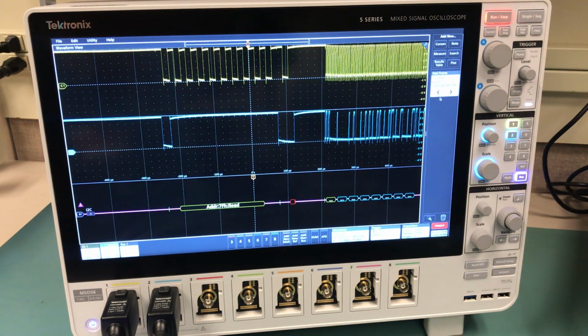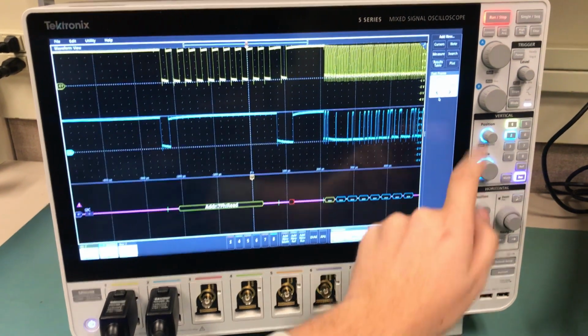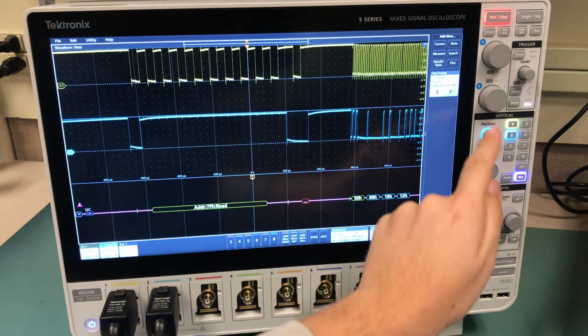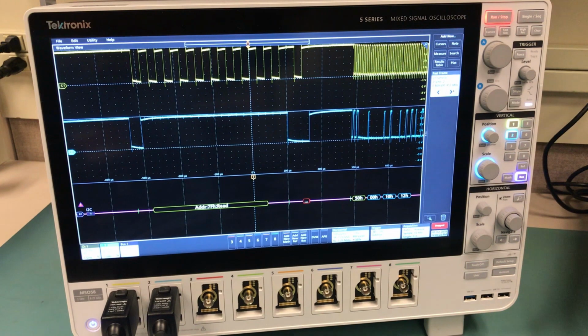With the badge on the right of the screen, I can cycle between the two trigger events, or frames, that were recorded. You can see a definite difference in clock speed as a lot of the hardware was still active when the bus restarted after our simulated dropout. We might use this information in reliability testing or in building a backup power supply on the board itself.